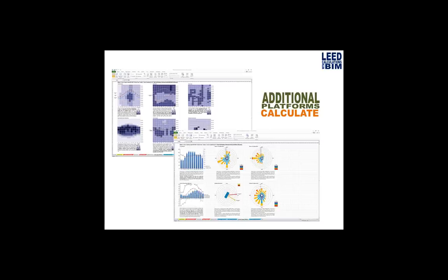You're not going to get the specific data that you need for those credits, but I think it's really helpful to understand this. So what we are doing here is we're extracting data from the weather files, and we're using pivot tables and pivot charts within Excel to graph temperatures, precipitation, humidity, cloud coverage, prevailing winds, directions, and velocities. And the point really is to better understand what the conditions at the site are and then identify some strategies early on, right? Because it's not really wise to wait for an energy model to know if your design is prudent for that climate zone. Most times energy models aren't really done until DD or until your design has progressed to a certain stage where at that point it's too late to make any major changes.